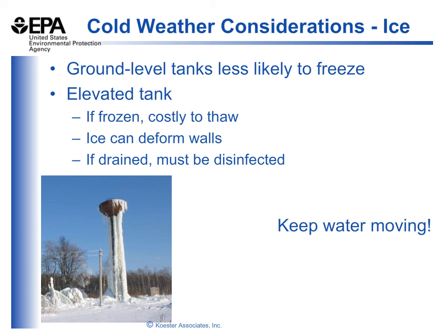Some of the utilities in northern areas also drain some of their reservoirs or tanks during the winter because they're not needed due to decreased water use, because nobody's watering their lawns or filling their pools at that time of year. This does simplify winter operation, but then creates a job of having to disinfect the reservoir or tank before returning it to service in the spring. We want to avoid the tank from being frozen solid because it will damage the structure and it'll be very costly to have thawed and repaired.